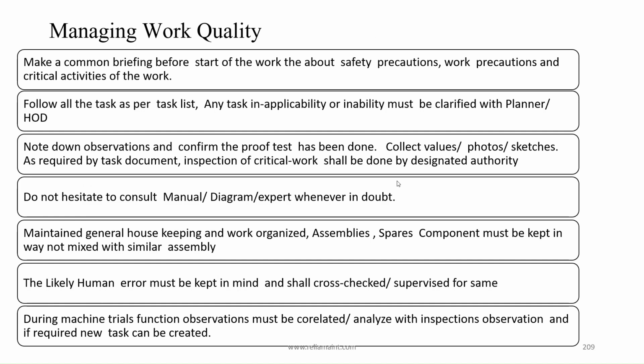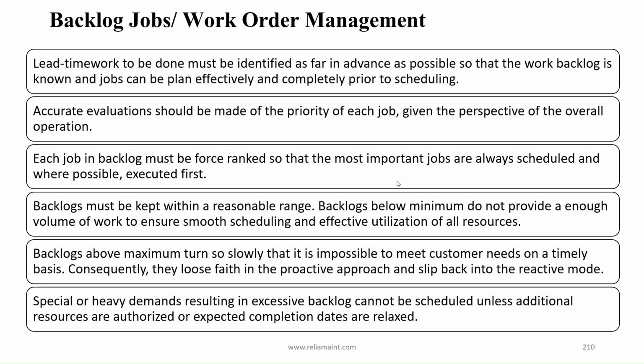Backlog jobs/work order management. Lead time for work to be done must be identified as far in advance as possible so that the work backlog is known and jobs can be planned effectively and completely prior to scheduling. Accurate evaluations should be made of the priority of each job, given the perspective of the overall operation. Each job in backlog must be force-ranked so that the most important jobs are always scheduled and, where possible, executed first. Backlogs must be kept within a reasonable range.